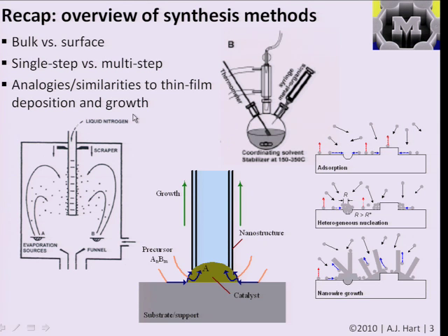And the example that we discussed briefly was growth of zinc oxide nanowires, where on a surface with some roughness, you get heterogeneous nucleation from the gas phase, i.e. formation of clusters of a critical size, just kind of like we're thinking about in the elementary model of solution growth. And then after that, because of the anisotropy of the zinc oxide structure, it's favorable for wires to grow along a particular axis. And we'll build more upon this model on Monday when we talk about the specific examples of nanotube and nanowire growth, how the size distributions of these longer structures evolve with time.